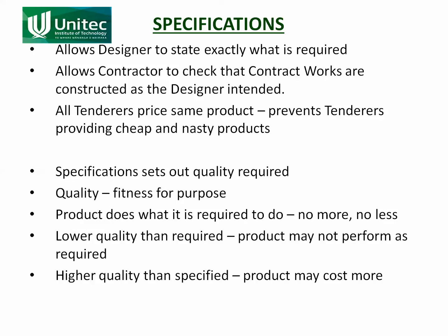What does he actually want? What quality of material does he want? What quality of workmanship is okay? And that means that when the tenderers are pricing the tender document during the tendering stage, they're all pricing the same thing. It's not like a tenderer can say, oh, we can use this cheaper product and reduce our contract price and win it using this cheaper product, which is going to break down after a few more years. It's not going to last the design life, but that's fine, it's not specified.